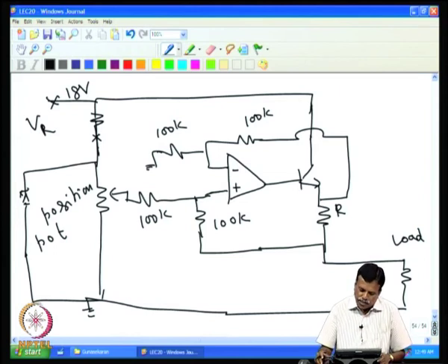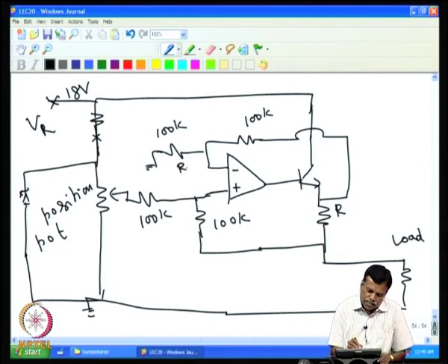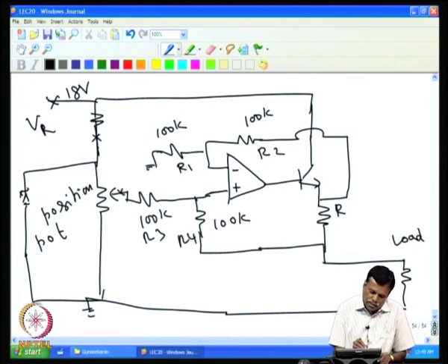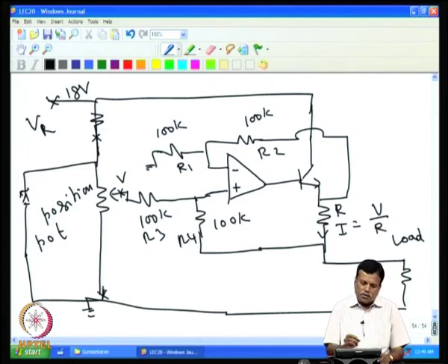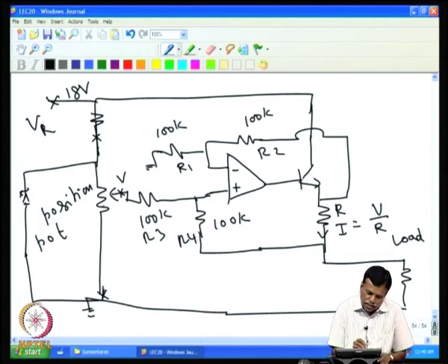In this, what we are trying is that we have these resistances which we have already discussed, for example, R1, R2, R3, R4 are equal. Then if this is say V with respect to ground, the current I is given by V divided by R, provided all 4 resistances are equal and this resistance is negligibly small.